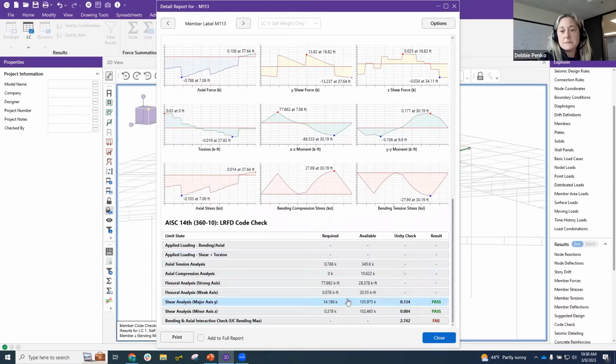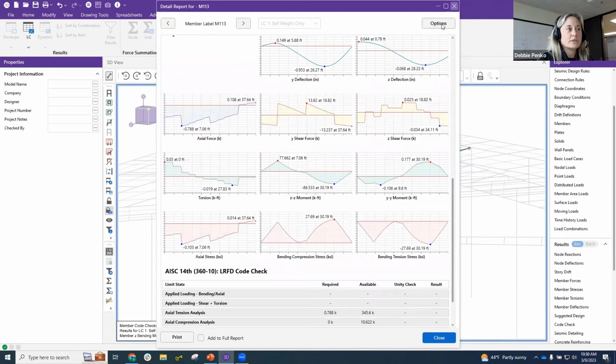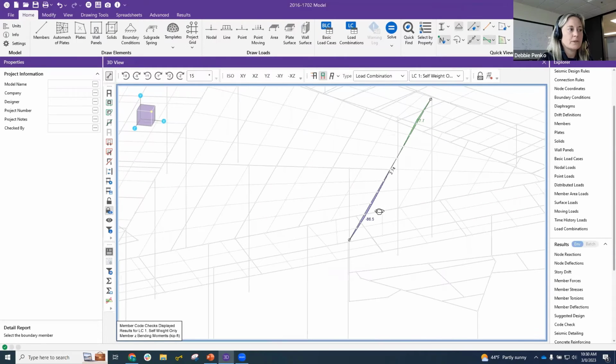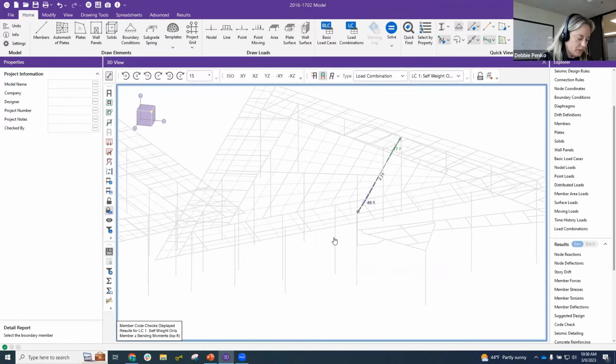It's a lot of times collective. The system, something is happening. So there's a lot of things tying into this member. I can see that from the axial forces, right? So there's stuff happening along the members. So this is kind of why zooming into that one member is pretty important. So I would definitely recommend Quick Find. That's a quick, easy way to jump to that member.